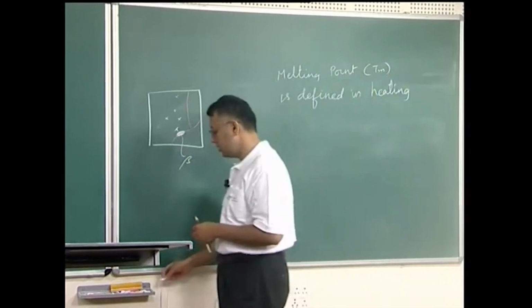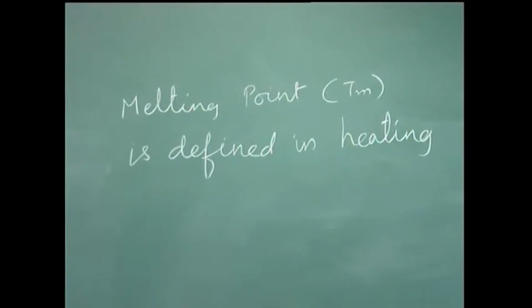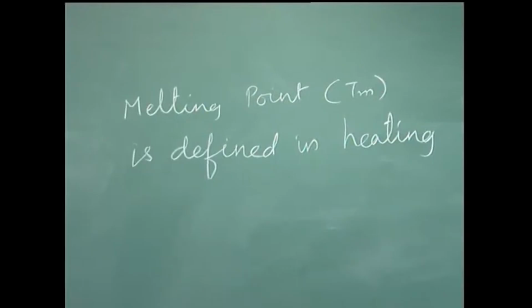This is a very surprising phenomenon: you heat, say for example, a copper metal, then suddenly at some temperature Tm, the entire lattice of copper collapses, and therefore you have the liquid state, which is very surprising, but nevertheless that is what happens. Now, suppose you are doing the reverse process of cooling the metal, then solidification does not start at the melting point. That means the freezing point is not the same as the melting point, and we observe a phenomenon which is known as undercooling.